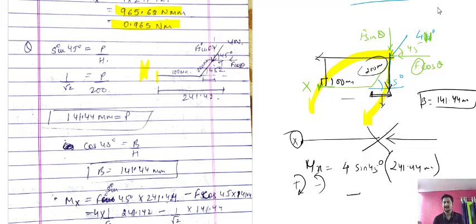Now this is clockwise and I have taken it as positive. The other is negative because it is anti-clockwise, and the anti-clockwise component will be F cos theta. Cos theta is cos 45, and the perpendicular distance for this point will be this distance. I am talking about the perpendicular distance. You can calculate it by using sin 45 equal to perpendicular upon hypotenuse.